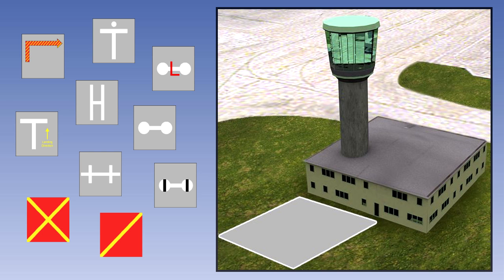As well as light signals, other ground-to-air signals are used to convey information to the pilot. A signal square is usually positioned outside the air traffic control tower or at another location on the movement area where it can be seen from the air anywhere in the vicinity of the aerodrome. In this area, ground-to-air signals are laid out to convey essential information to pilots unable to communicate by radio.